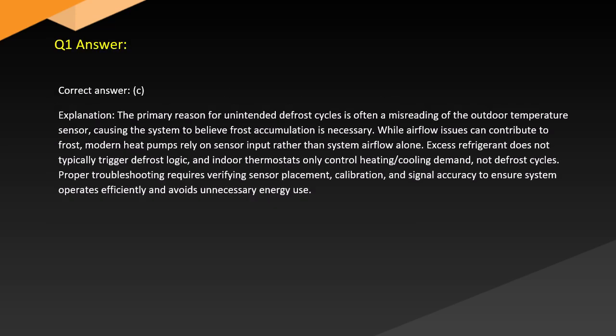Answer. Correct answer: C. Explanation. The primary reason for unintended defrost cycles is often a misreading of the outdoor temperature sensor, causing the system to believe frost accumulation is necessary.